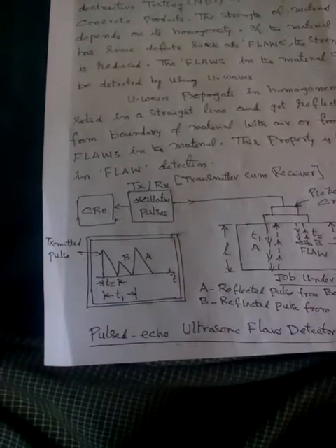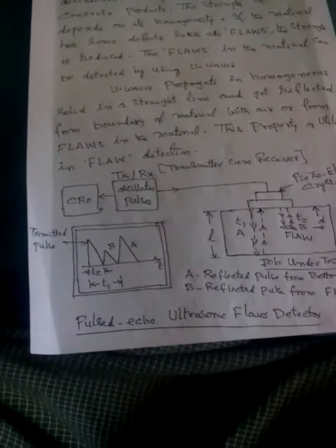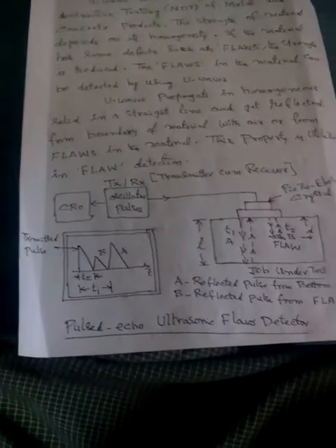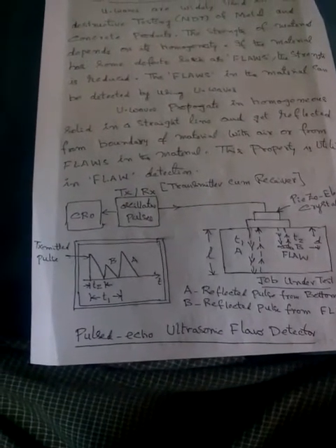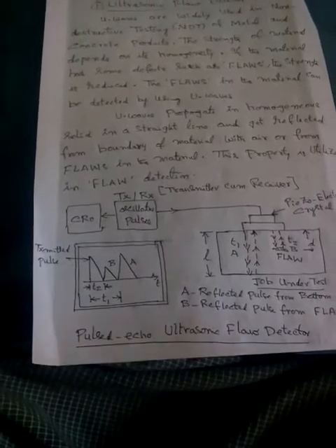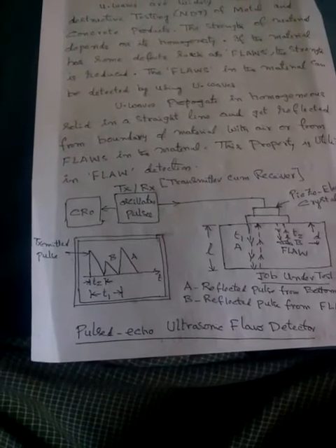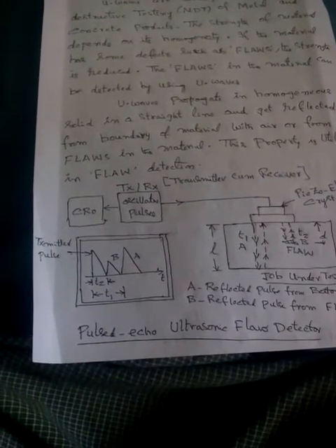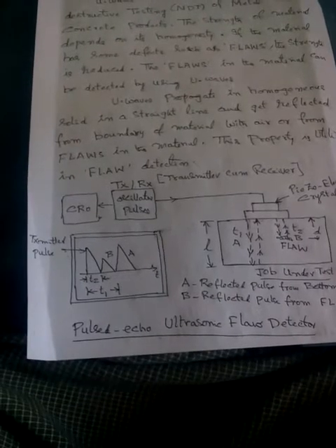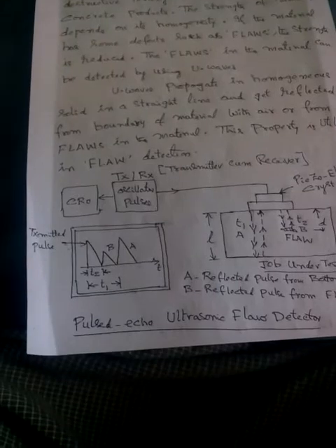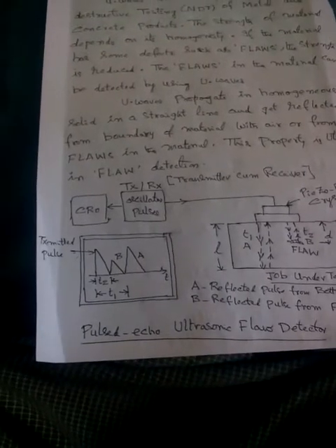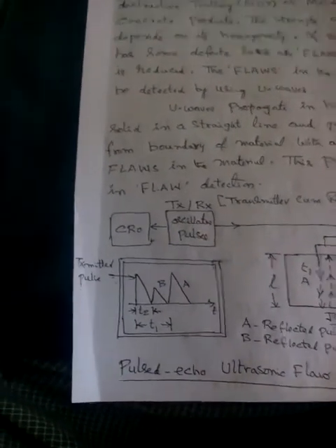So we have to move the crystal, piezoelectric is on the top surface of the material, so that ultrasound goes into all parts of this material, that is job under test, so that we can completely detect the material is perfectly alright or if there is any flaw or defect in the material. Okay, that is how it works.